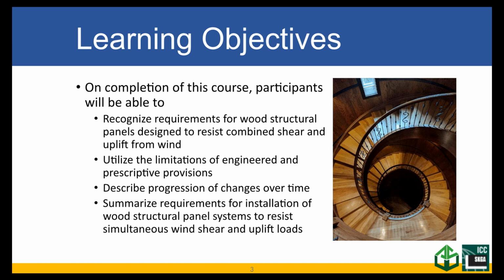We're going to look at both engineered and prescriptive provisions. And when I say prescriptive, that's going to be based on that wood frame construction manual document, but that is what we would call an engineered prescriptive solution, meaning there are calculations for the prescriptive tables that have an engineering basis.